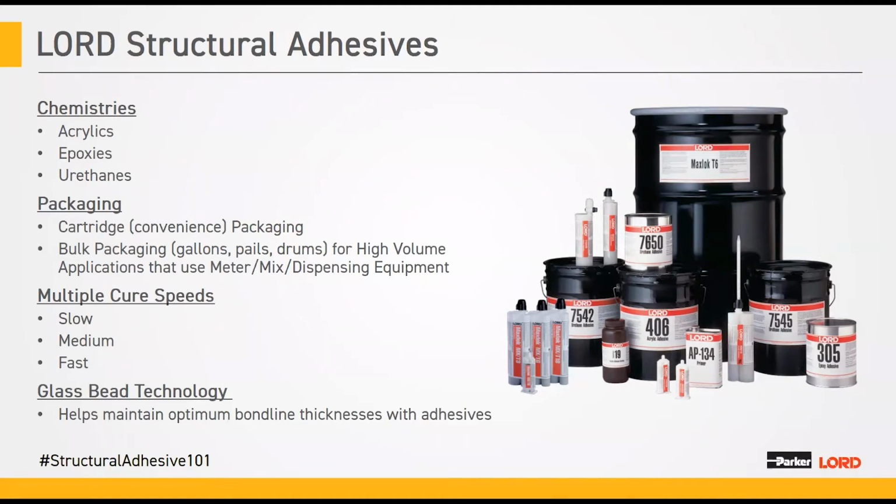Many of our products offer multiple cure speeds, so they have a consistent adhesion and consistent physical properties across a wide range of different open times. So we may offer a 3 to 5 minute open time for a faster product, and maybe a 60-minute open time for a slower product. Glass bead technology is something we offer in some of our products. This helps maintain the optimum bond line thickness with the adhesive and prevents too much adhesive from being squeezed out.